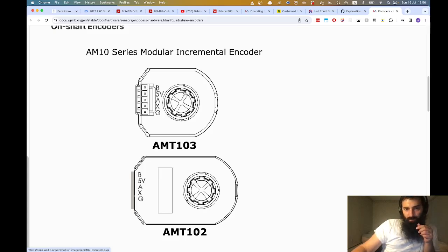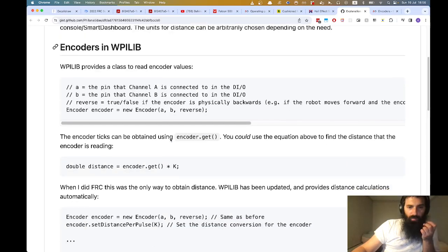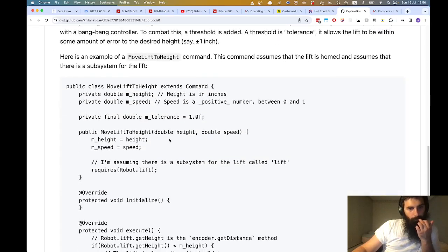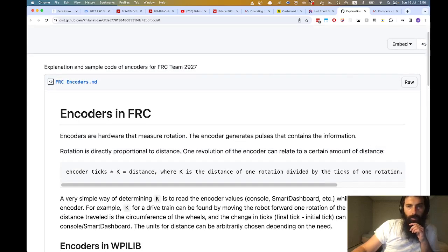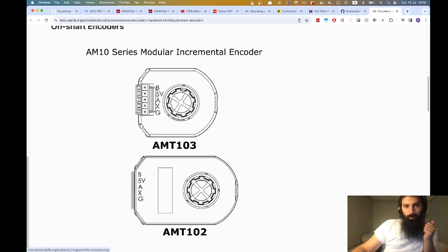So if I spin this just a little bit, let's say it pulses one time, which tells the sensor, okay, I have turned one pulse. You can find in the specs that a complete rotation is a certain number of pulses. I think in the code it's usually 4096 pulses. It's a known value which you can just look up. So as this encoder spins, it says I've seen like 1,000 pulses, and because you know how many pulses equal one rotation, you'll be able to know exactly how far this thing has spun.